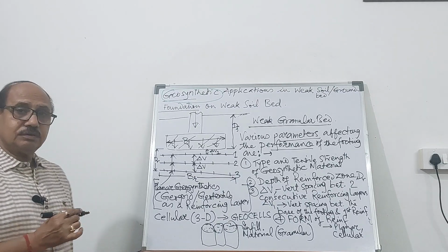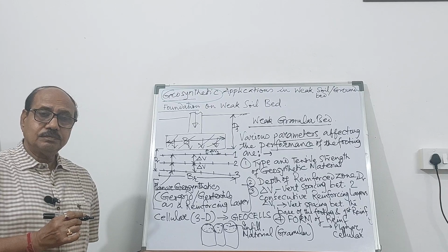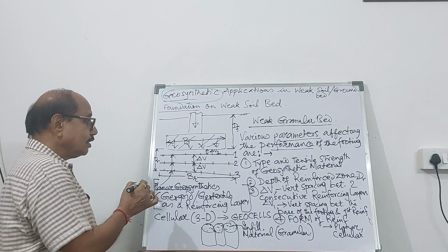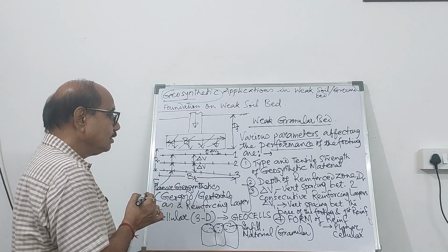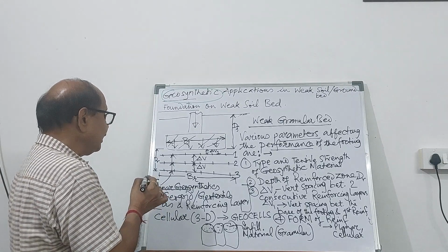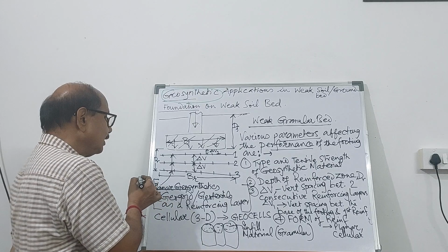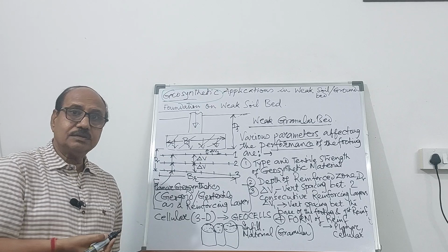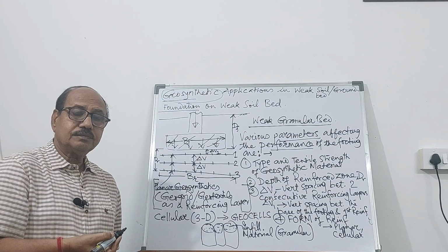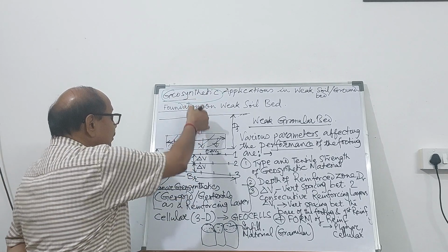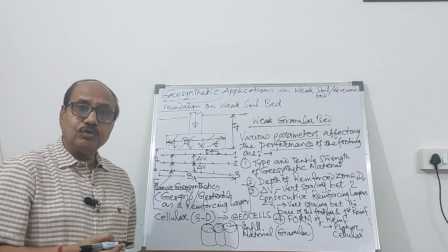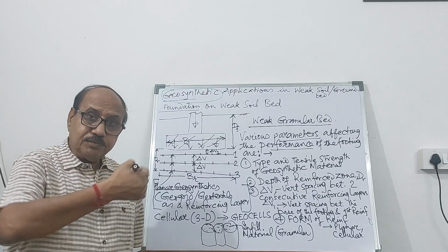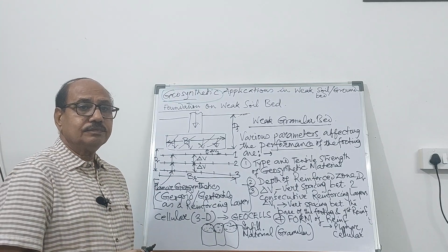That's very important. The depth of reinforcement is equally important, because when you apply the static loading, how deep is the pressure bulb going?